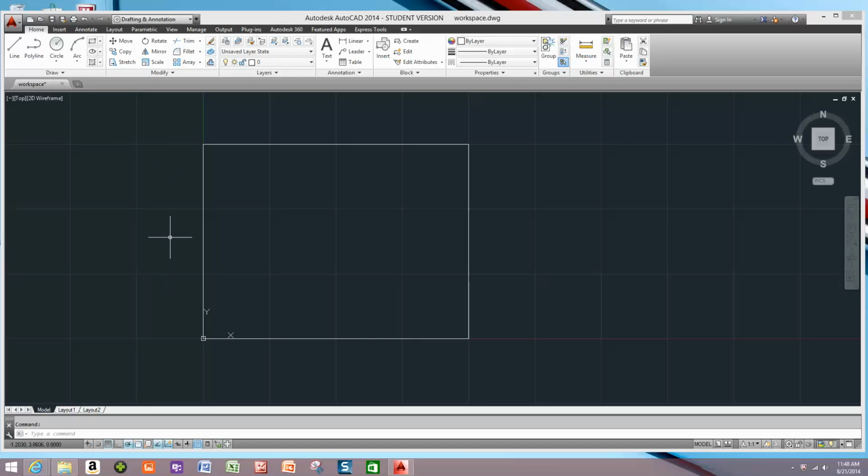The last time that I had you guys set up your different settings over here, I had you turn on a couple and I had you turn off a couple. The ones that I have over here, which are your dynamic settings, I think it's going to be a lot easier if you turn off your dynamic setting right here. So where it says dynamic input, I need you to turn that off, okay? And basically, the only thing that's going to do is you're not going to be able to see any of the angles, and there's not going to be anything that you can actually see when you're typing on the actual workspace itself.